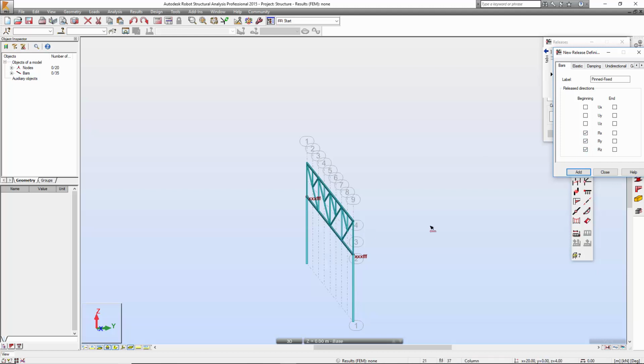No, I don't think so, because with the truss, if you get a hinge at that top, you can see that it can easily fall down in the Z direction, in the Y direction. So it's an unstable structure because it can rotate along this axis, which is the x-axis, along this line from this point to this point. It's like a mechanism. It's like a hinge. It's like a door, it's rotating. It can't stabilize the structure. So this is definitely not what we want.